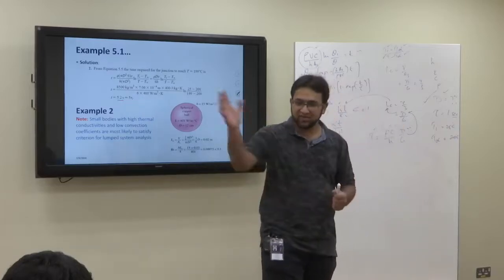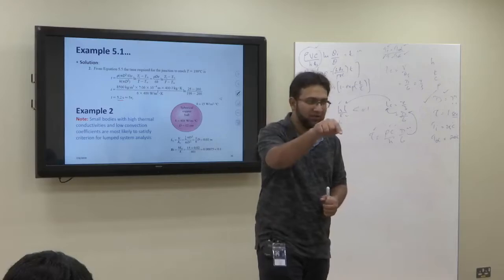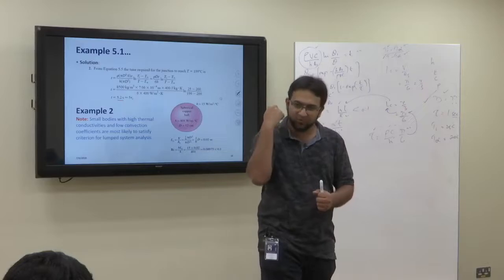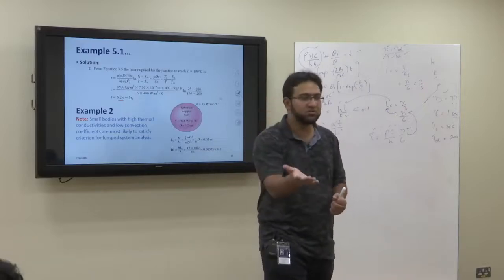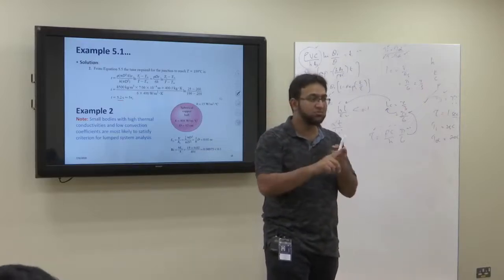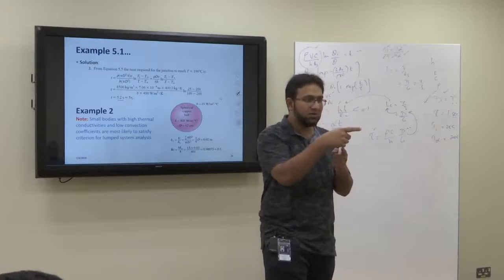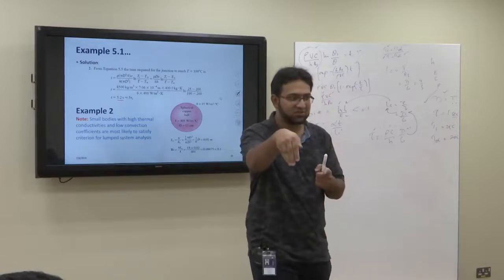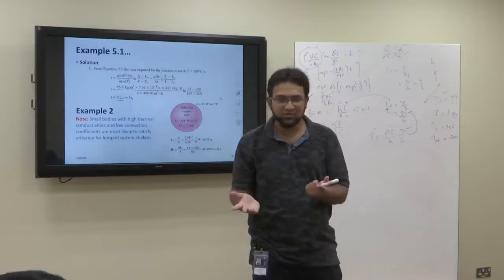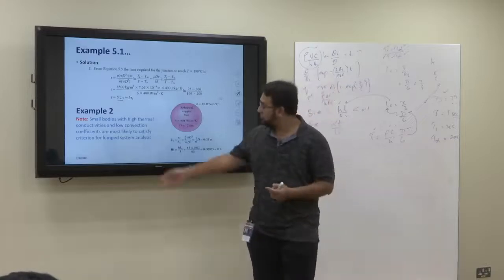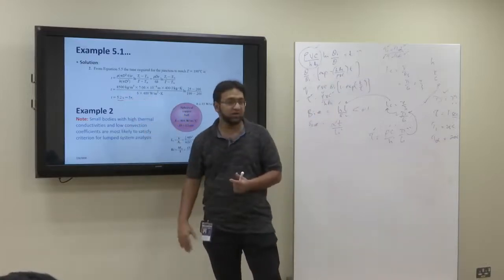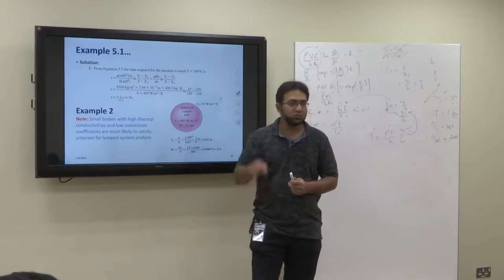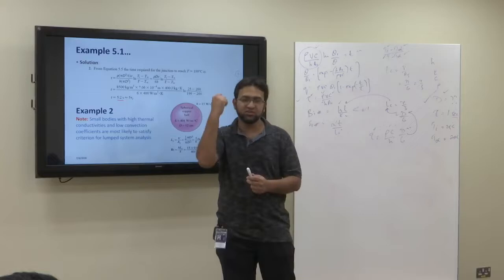Suppose there was a gas stream and you put the thermocouple in it and you remove the thermocouple from the gas before 5 seconds, it will give you the wrong temperature, because the thermocouple should reach the same temperature as the stream to give the right temperature. So the time for it to reach 199 degrees centigrade is 5.2 seconds. So if you put the thermocouple and remove it in 2 seconds, it will not be correct.